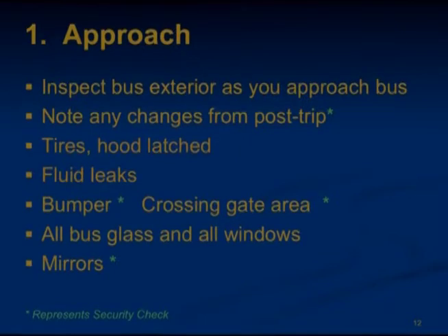Okay, so let's start with step number 1, which is the approach. As we approach the bus, look for any changes to the bus or surroundings from the post-trip inspection when you last drove the bus. Has there been any vandalism, damage, or graffiti? Signs of vandalism could be debris on the ground, flat tires, or open doors or hoods. A thorough security awareness sweep of the exterior of the bus should be performed prior to entering the bus.